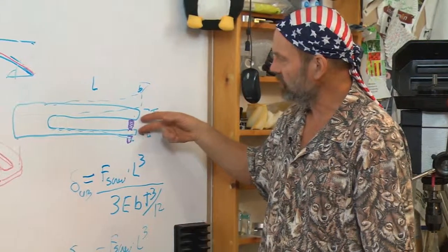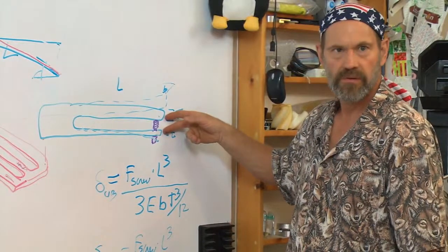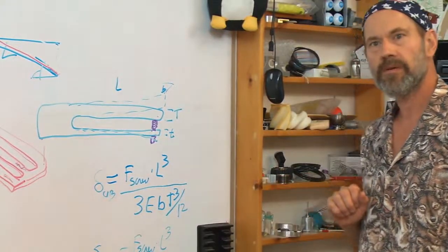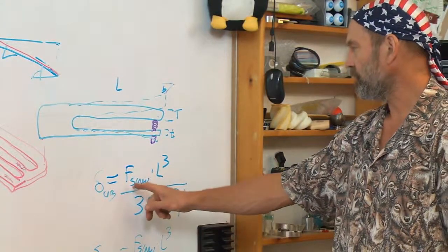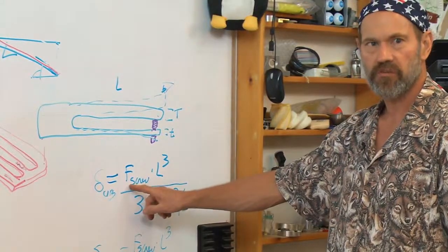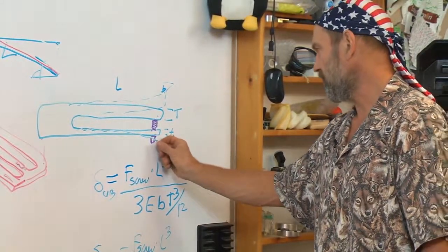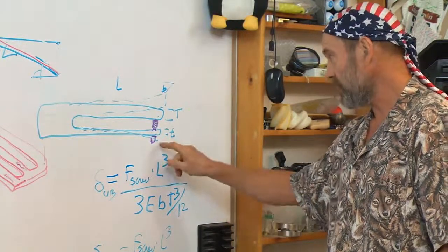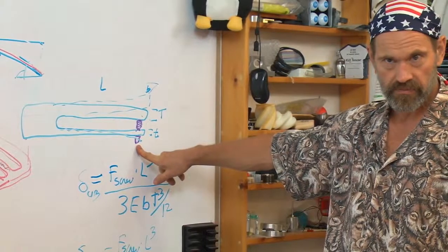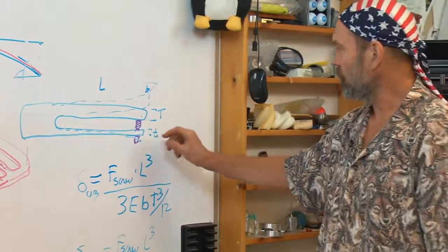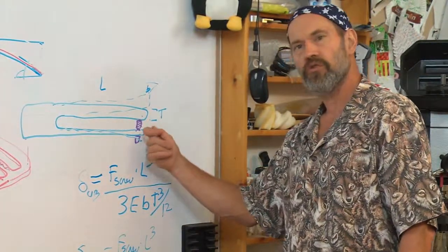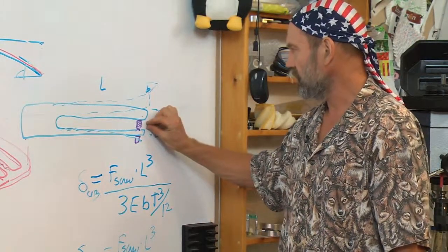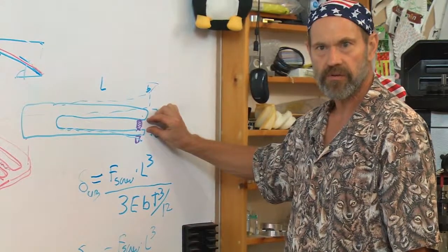So what does that tell you about what happens with the upper beam with respect to the lower beam? Well, when you apply the screw, it never really applies a force so much as when I'm adjusting this thing, what I'm really doing is applying a displacement to the screw. So, for example, one turn of the screw, if the screw has a pitch of 1 millimeter, means the screw will lengthen by 1 millimeter.